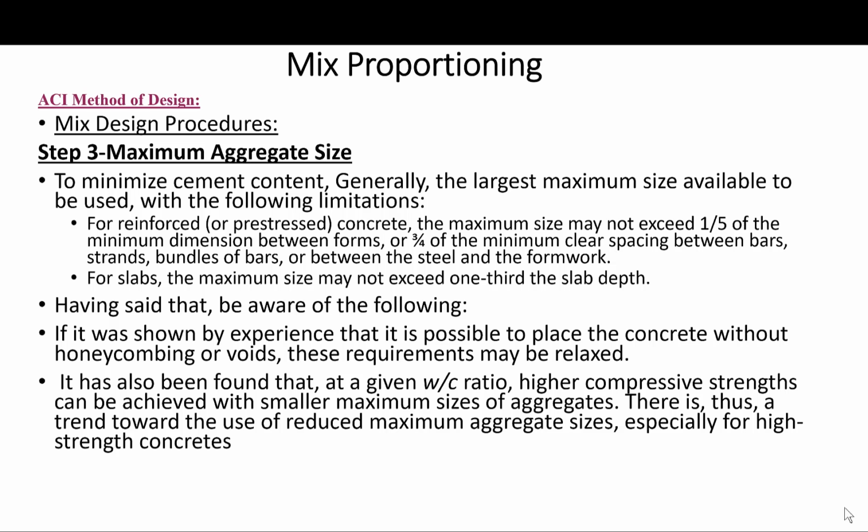Having said all that, be aware of the following. If it is shown by experience that it is possible to place the concrete without honeycombing or voids, these requirements may be relaxed. It has also been found that at a given water cement ratio, higher compressive strengths can be achieved with smaller maximum sizes of aggregates.